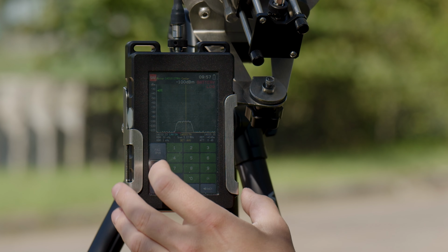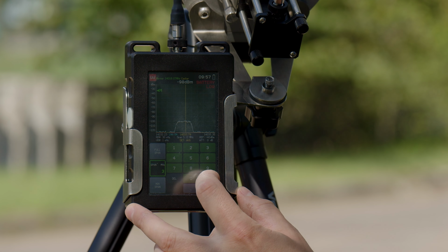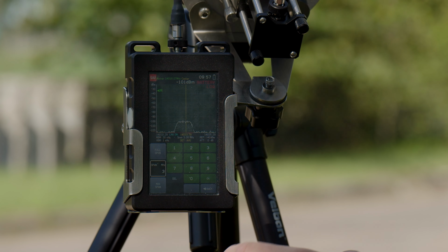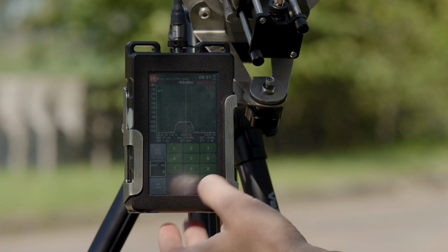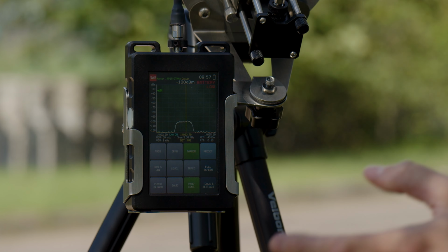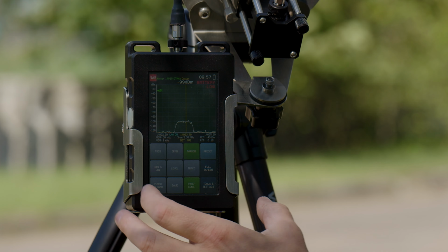So right now it's settled on the 3 MHz span. So now we have a clear signal. We see it, and right now, if we want to verify whether the signal is in the correct bandwidth, we go to the power in band settings, and we set the signal width to 1 MHz.